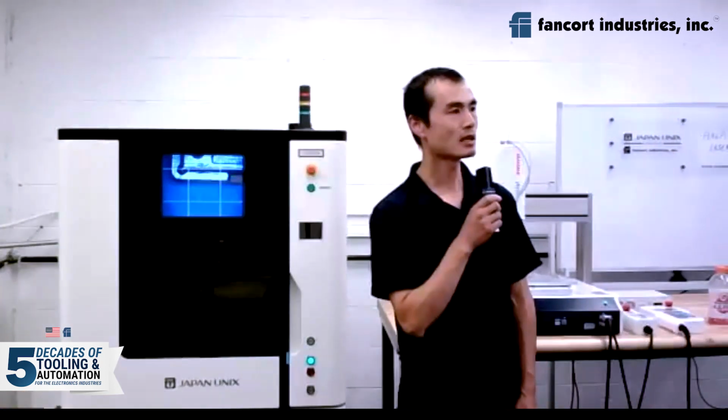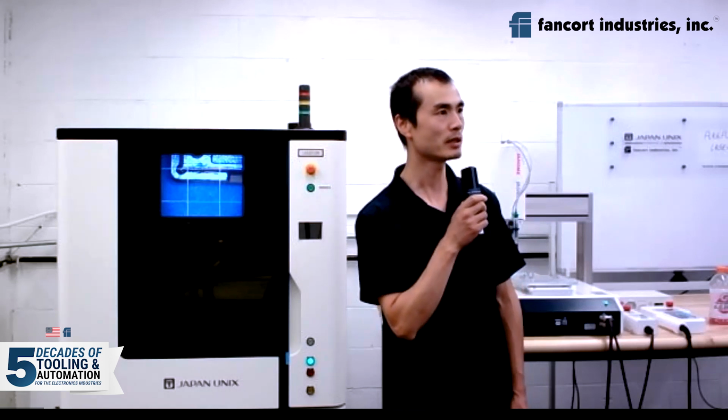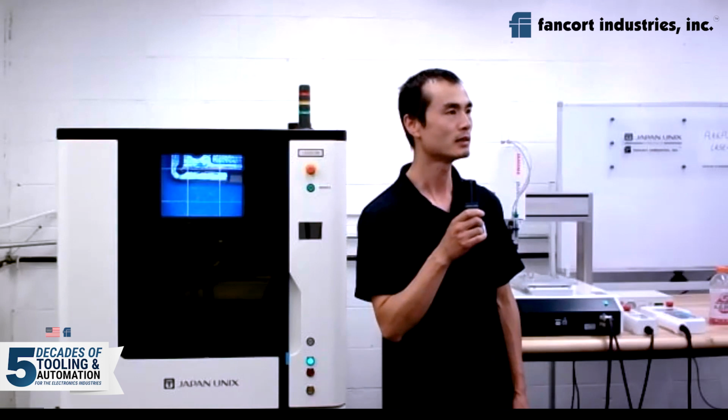The question is, what has our experience been with multi-layer boards? Kitamiya, can you maybe help with that one a little bit? Thanks, Kit. Okay, yes, it's a great question. So for multi-layer boards, I think sometimes we might need to use a hot plate to preheat the board to a certain higher temperature, then use an area laser to cover such multiple points.